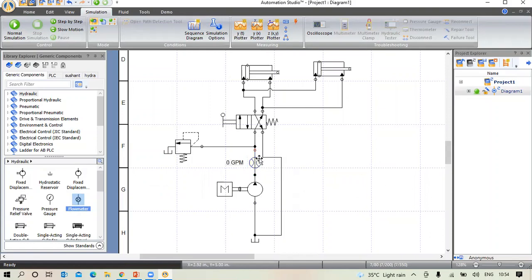And you can see the red port options, because a red port indicates no proper connection between these components onto this line. So select the component, press the shift key and remove it from here.